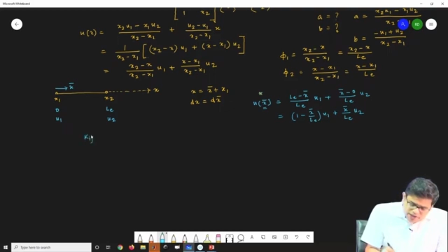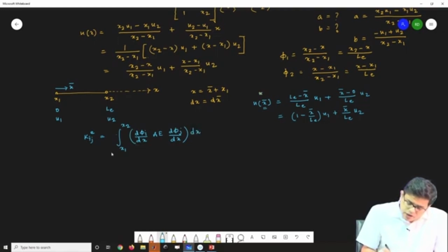So K_ij for a particular element, in the global coordinate system, was the integral from x1 to x2 of dphi_i/dx times AE times dphi_j/dx, dx.